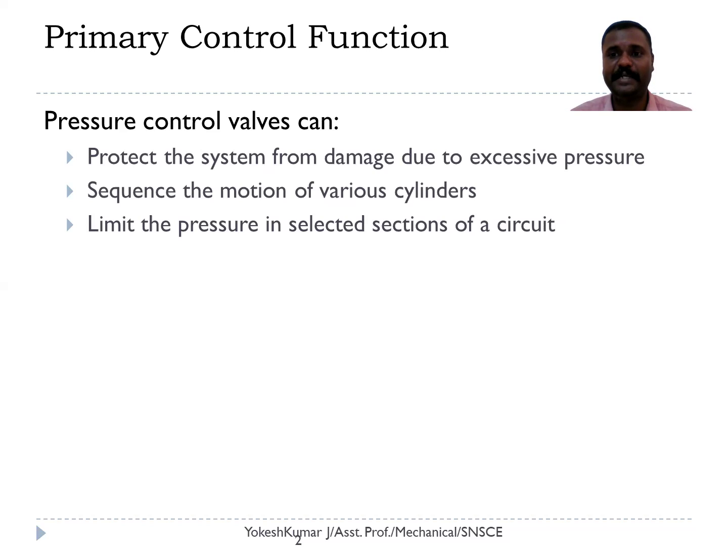For some typical applications, we need to use less force for the cylinder. Those parts may be fragile in nature, for example water bottles. If we apply too much force, it tends to crush the bottle. To overcome this, we have to reduce the pressure of the valve, and thereby reduce the force of the actuator.